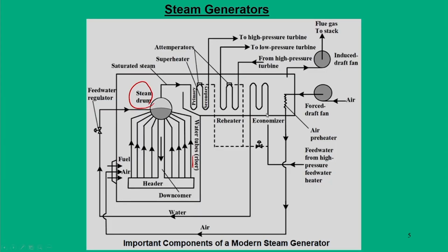Now, another unit is the economizer. The word economizer essentially specifies how economically you are using the energy, which is nothing but exhaust, and how you are going to use it for initial preheating purposes. So, the economizer does some of this initial preheating. Again, we also require the air to be preheated. That preheating concept is integrated with what we call air preheaters. So, basically wherever heat addition or heating is required for different parts of the power plant, that is integrated with this steam generator, and ultimately the entire energy comes from fuel air combustion, and here the fuel is mainly fossil fuel. So, this is the overall concept of the steam generator, which is replicated in this diagram.